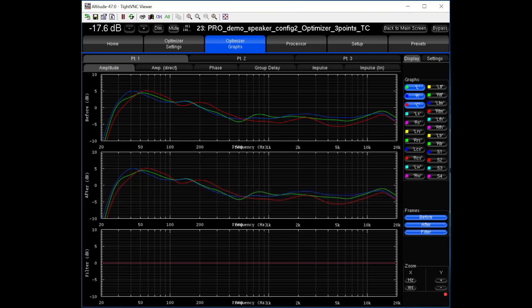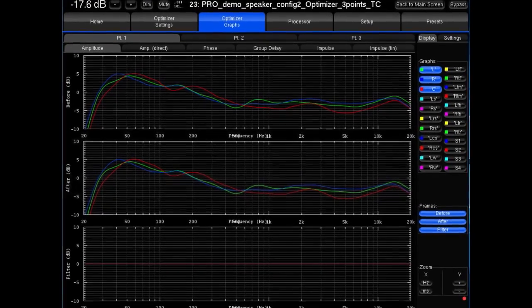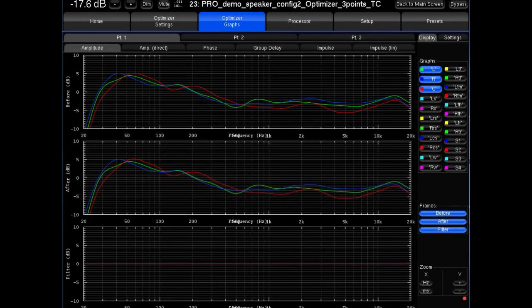This is unequalized response of the left, center, right speaker in our listening room here, and there's a lot more energy at the low end, and then it shelves down, and right about where I said 500 hertz or so, it sort of flattens out, and that change in response there is due in part to that high directivity of the speaker and the influence of the room.